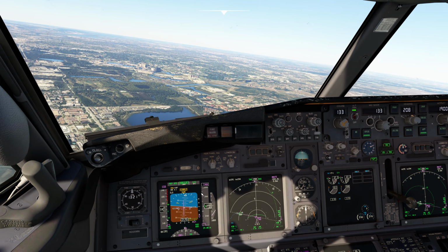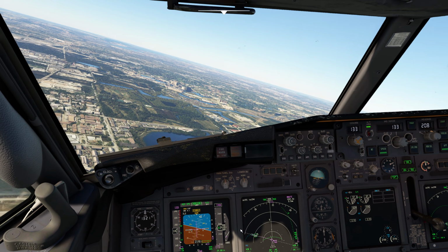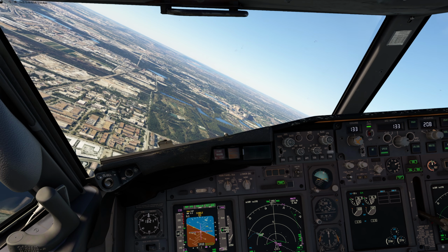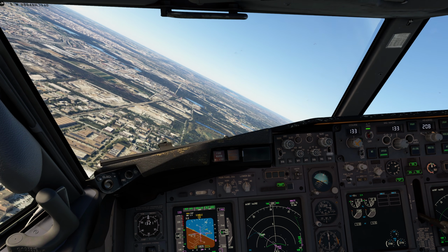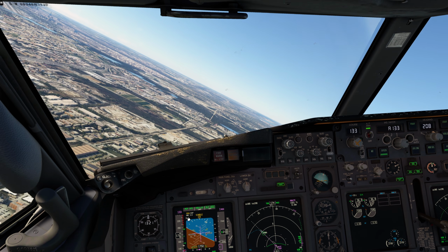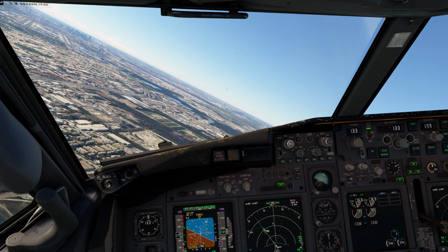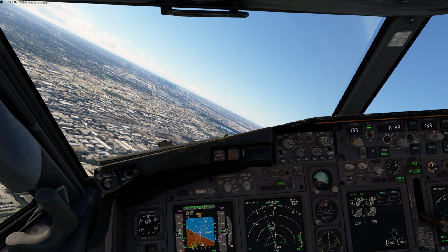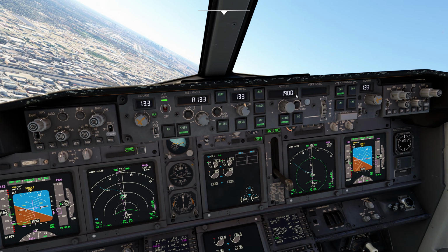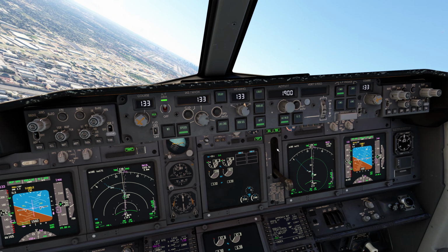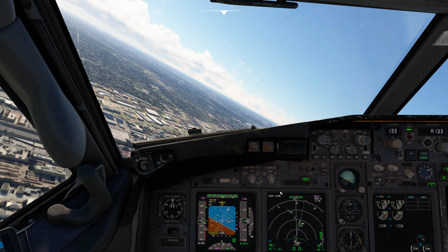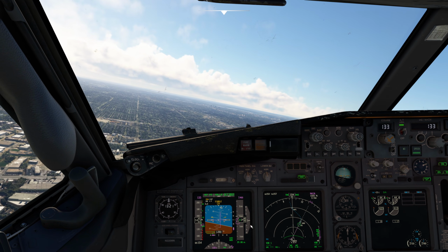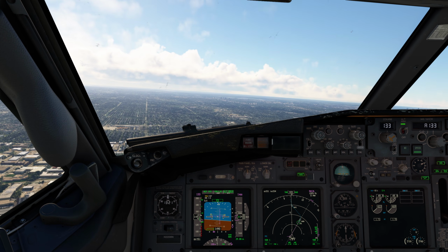Okay, the VOR localizer has been captured here, you can see. And the autopilot is starting that turn inbound. Slow it down a little bit, let's get some speed brakes in here. Okay, let's get the final approach course plugged in to our heading bug, 133. 133 is set. VREF speed is set, and 1900 localizer altitude is set. And we have the runway in sight there. Autopilot's going to have a little bit of trouble capturing it, I think, so we're going to go ahead and disable autopilot and manually fly it in.